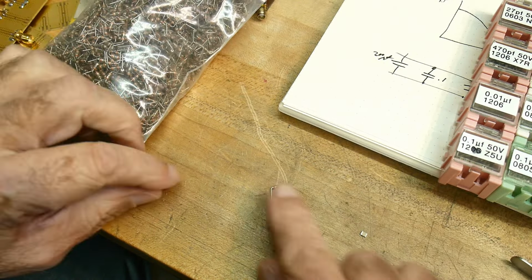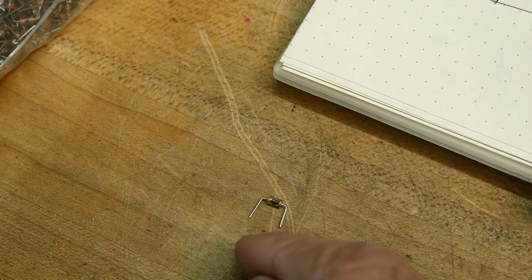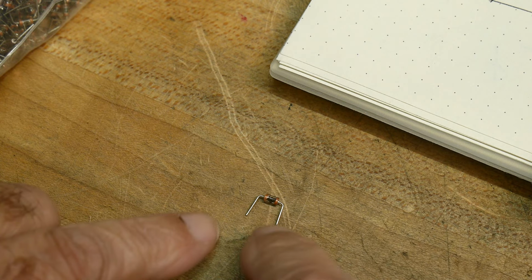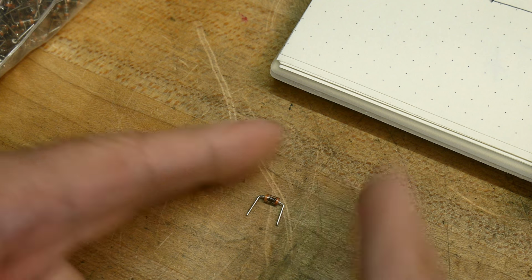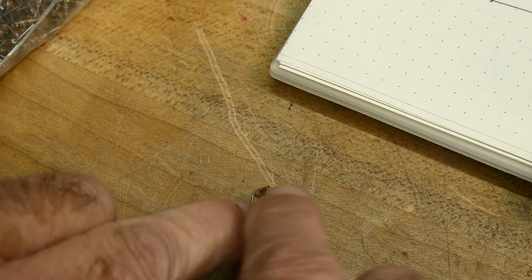The reason I want to talk about these is we've seen the effect of the inductance in this problem. The capacitor plus the leads and everything add inductance, right? So how are these constructed? Well, there's a little plate in there and a little chip capacitor, all bonded together, but it adds inductance, right?